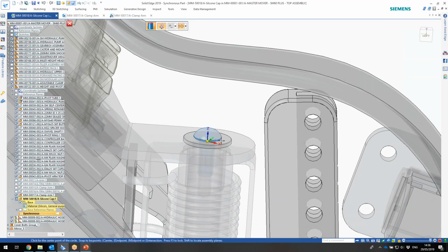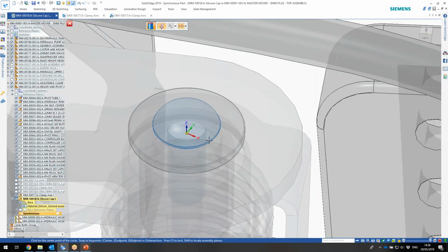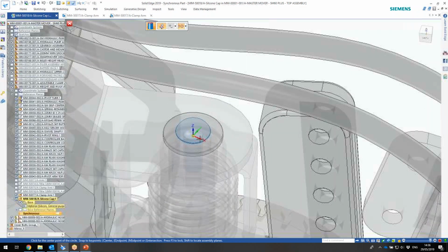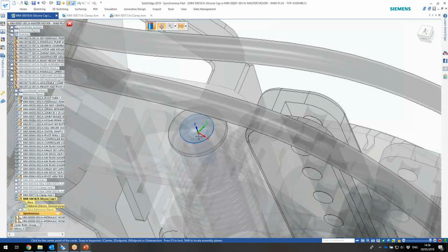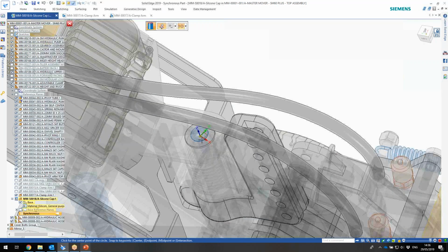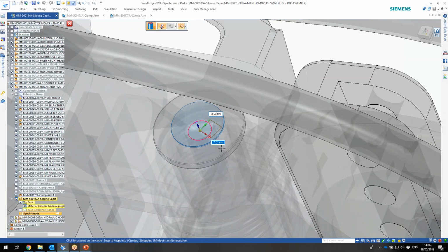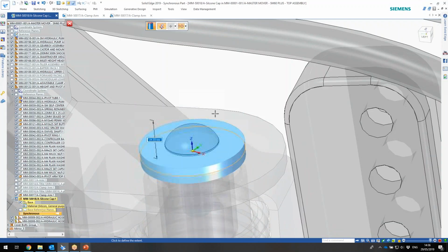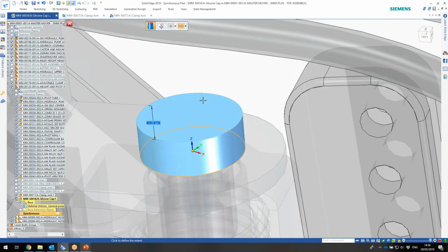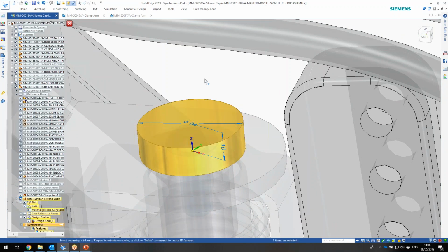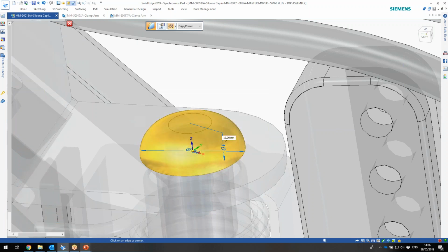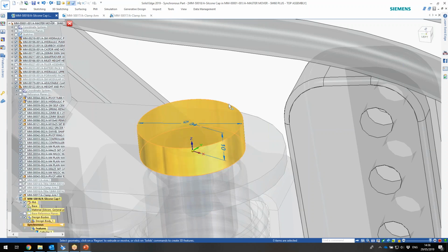Create a cylinder. I'm going to be creating it on that plane there. F3 from the center, bringing it out 34. Now we don't want to be going into the model, so add shift again, coming up 10. Add some rounding, and it's going to be 10. Oh, not 10, sorry, 5.